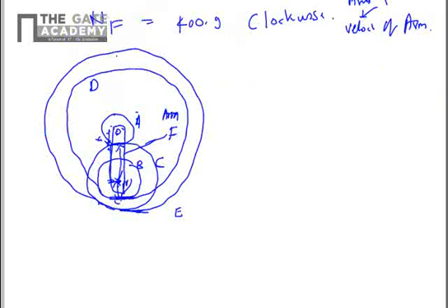For that we have to look at our diagram again. Now we don't know the number of teeth on E, so first we have to find that. If we consider the radius RE, it will be equal to RA plus RB and then again RB, so RA plus 2RB. You can see this more clearly here.